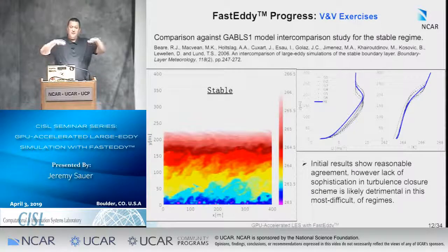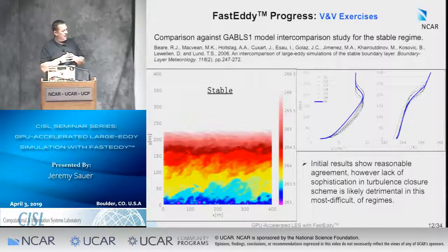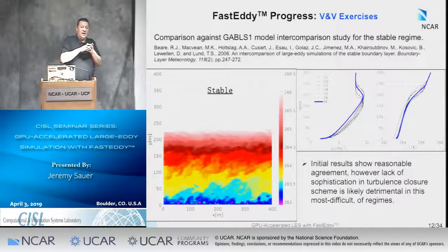This is because stability tries to damp out turbulence. And so what you find is capturing the proper range of eddy scales and the turbulence cascade across those scales is very, very difficult for LES. You really have to push your LES to very fine resolution spatially and temporally.